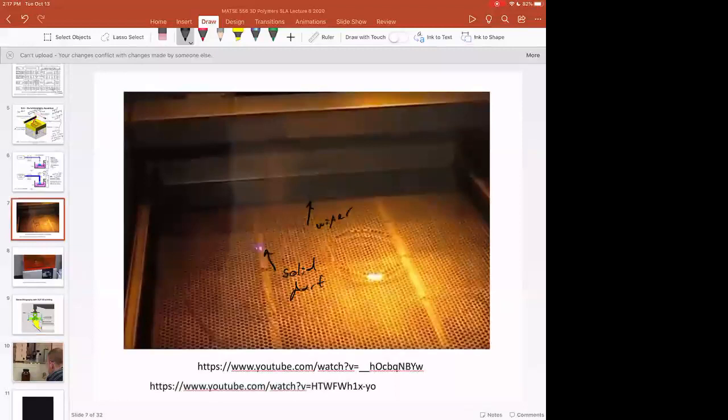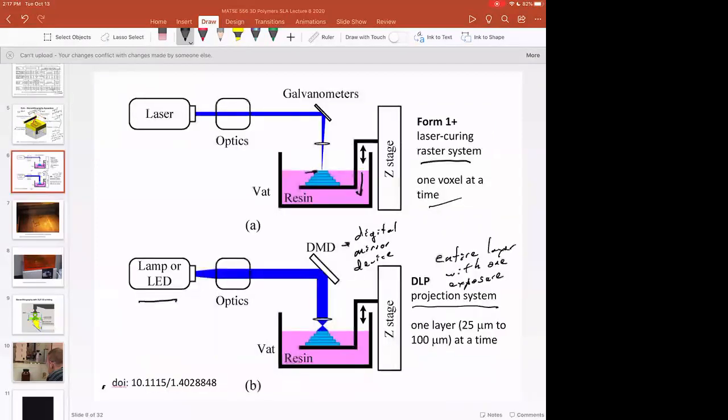So even though your layer height might not perfectly be controlled here, the very top surface of the resin is not necessarily as hard as the rest of the part, and that's wiped through with new resin. And so this picture of layer by layer, these are not perfectly hard layers like we think about in material extrusion AM.